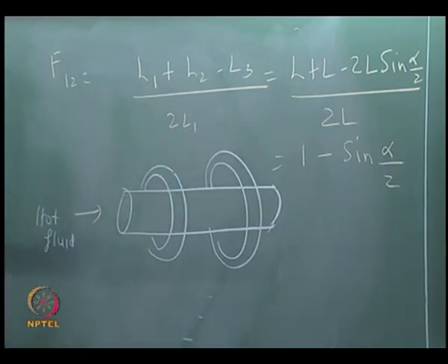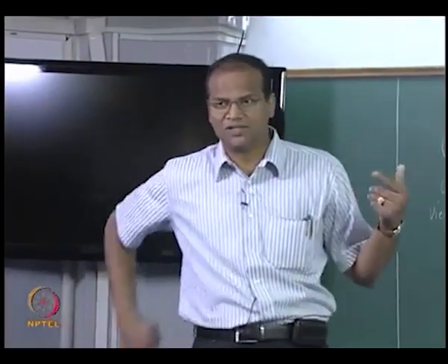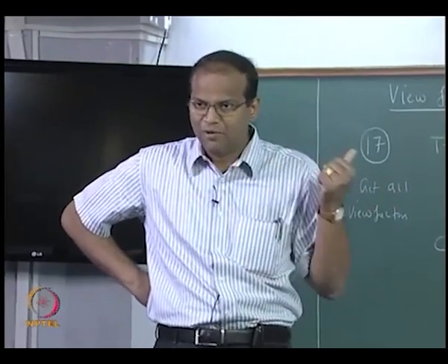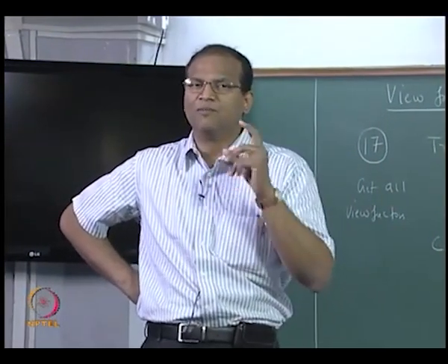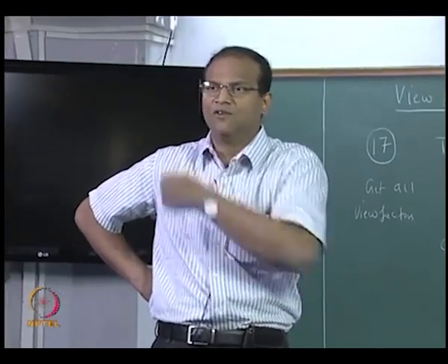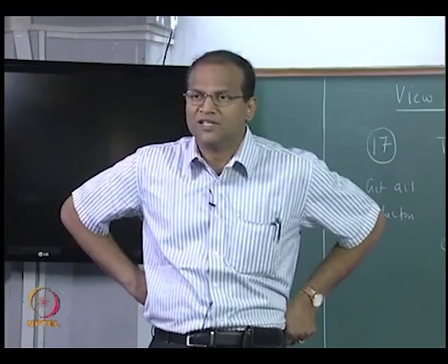Then you have to consider the view factors, and if you want to solve the combined convection radiation problem, it is very involved. 10-15 years back we were giving this as MS projects, MTech projects, but not any longer. Are you able to understand? So we will use different profiles, different fin heights, different thicknesses, we will optimize what is optimum fin configuration, what material, or if the material is fixed, geometric optimization.